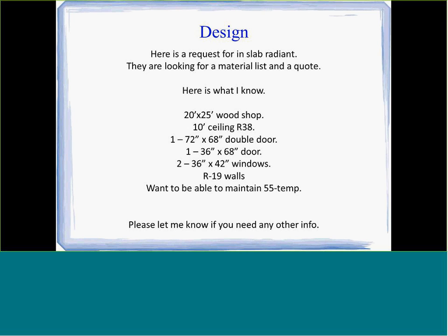ceiling. We got a 72 by 68 double door, a 36 by 68, basically a man door. We've got two windows, R19 walls. They want to be able to maintain a 55-degree temperature. Please let me know if you need any other info.